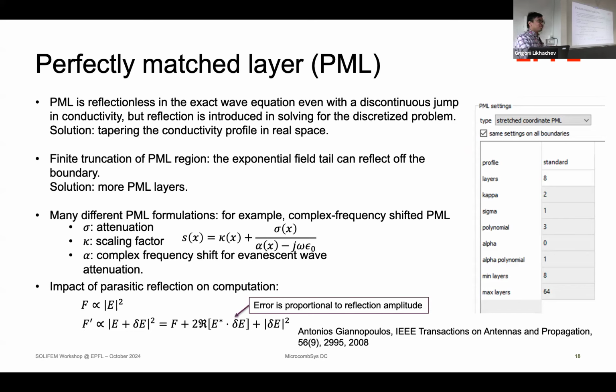But you don't need to do all of this. FDTD Lumerical has everything built in. So if you just choose PML, it works in general. But if you face some error in your FDTD, or if your simulation diverges, then you might need to look into this.